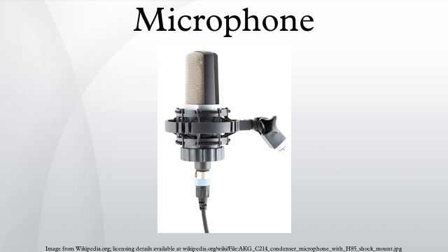Carbon microphone. A carbon microphone, also known as a carbon button microphone, uses a capsule or button containing carbon granules pressed between two metal plates, like the Berliner and Edison microphones. A voltage is applied across the metal plates, causing a small current to flow through the carbon. One of the plates, the diaphragm, vibrates in sympathy with incident sound waves, applying a varying pressure to the carbon.